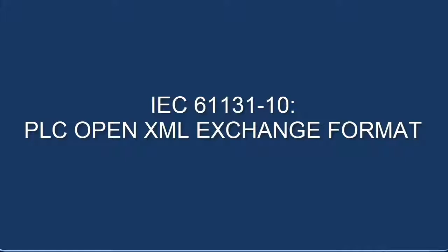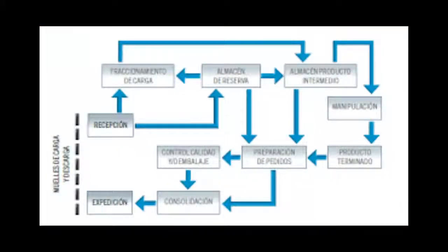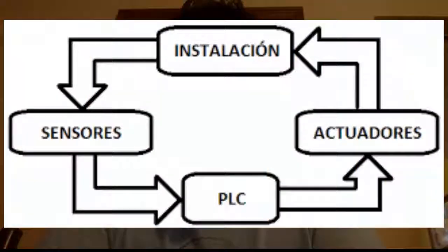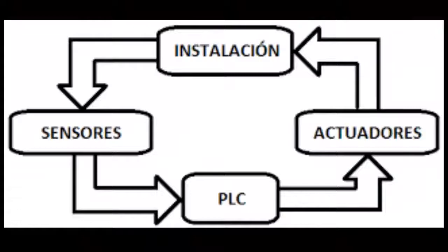IEC 61131-10, PLCopen XML exchange format. This is the part specifying an XML-based exchange format for the export and import of Part 3 projects. The exchange format specifies the corresponding XML schema. The XML schema is independent of the PLC vendor and is part of the specification.